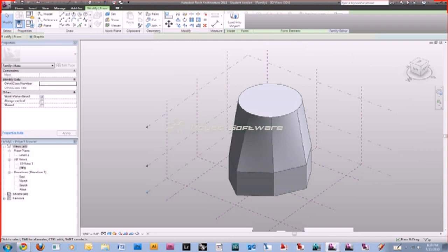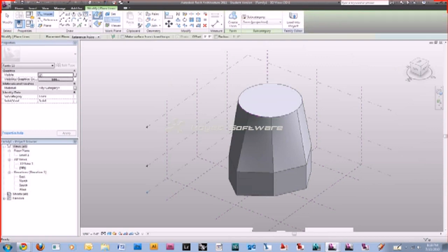So let's say in SketchUp, if you wanted to make a void, you would just draw a shape on this and then push it down. It works similarly in this program. Let's say we wanted to put a circle hole down the center of this. First we select this face and then go to our drawing tools. I'm going to select circle and draw a shape on that face.